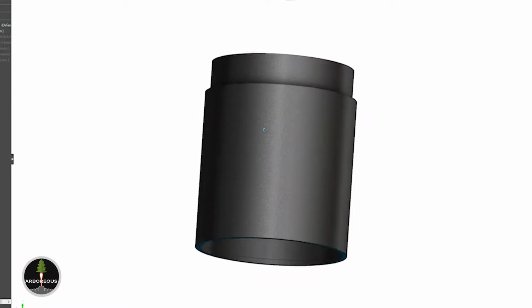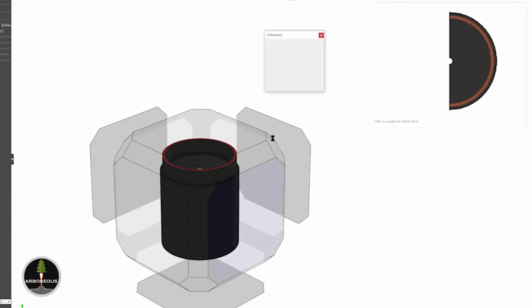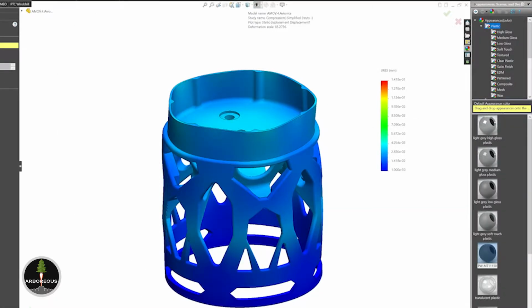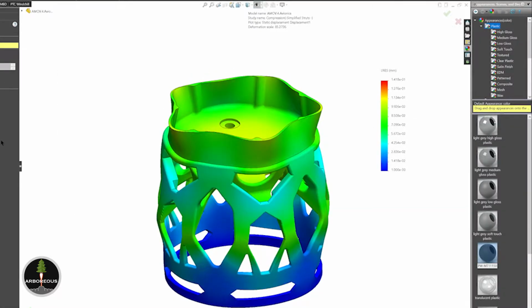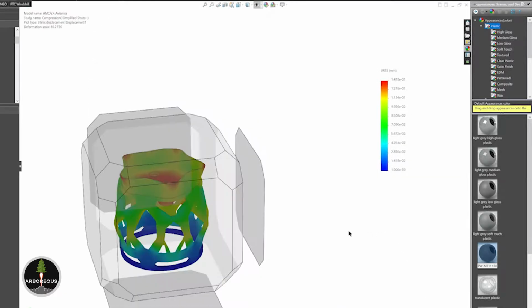The design started as a simple body tube with a thick bulkhead, but after being run through the topology optimization software in SolidWorks, the design changed drastically. The unique geometry is a result of test conditions set on the part, such as mounts for equipment, shock cord retention, as well as the material properties and load conditions.